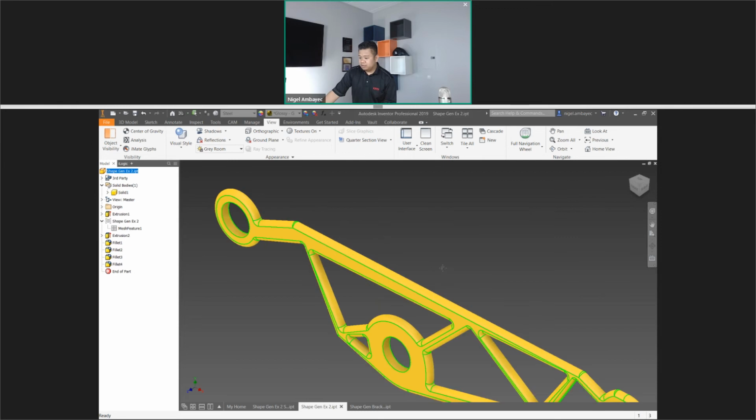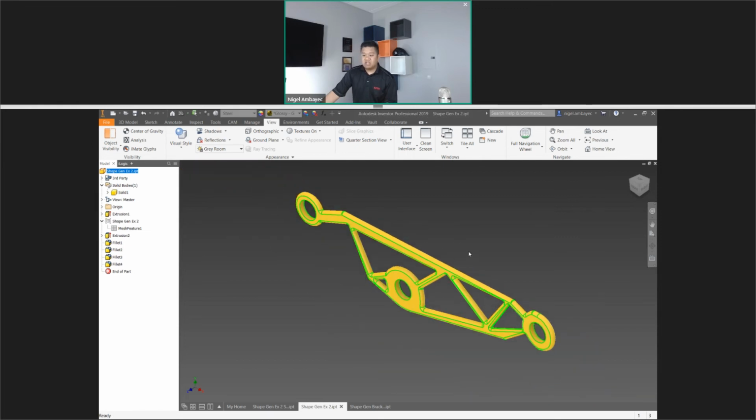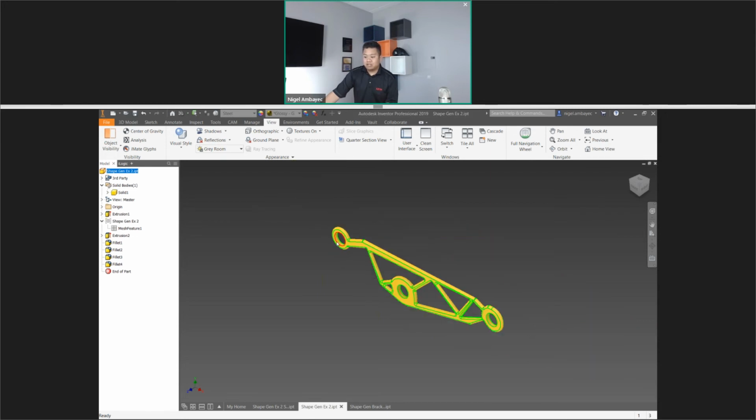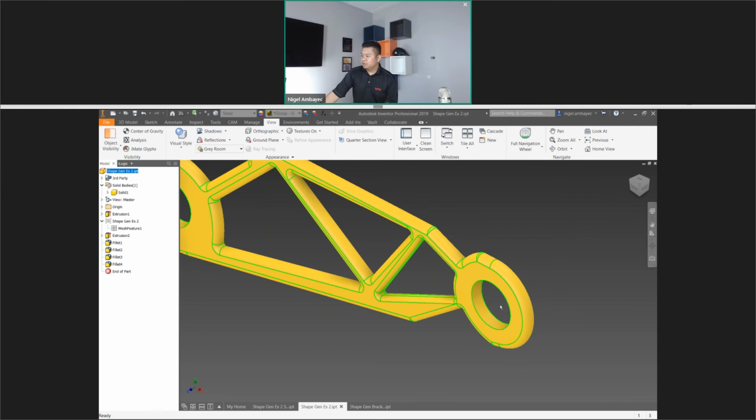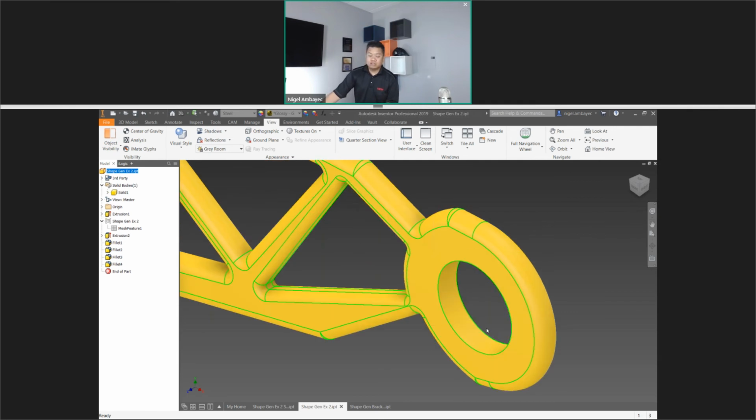We've got this shape. The next step, probably, is to take this into a simulation. I'm not going to do that right now, but if you do, you can use a lot of the same setup you did before, right, with those constraints. I'm going to pin it here, constrain it here, and apply the load here. And for those people who asked if I could apply the load to a particular point in this circle, you totally can. Go ahead and split this face. You're going to create an edge down here where I'm highlighting. I can sketch on that if I wanted to, but create that edge, and then apply the load to the edge. Do not apply the load to the face. And then you get that load at that particular location.